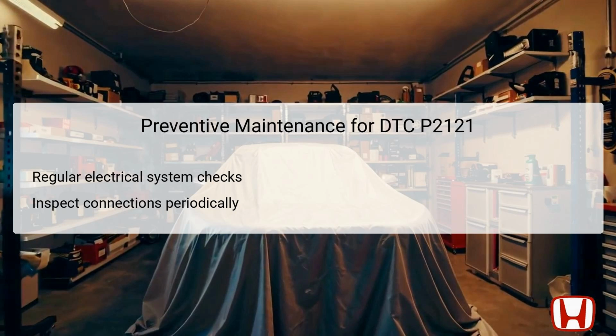It is particularly important to observe conditions of terminals, ensuring they remain corrosion-free and securely connected. Besides physical inspections, ensuring that all electronic components are updated with any technical service bulletins can improve reliability. Ultimately, proper maintenance reduces the risk of sensor malfunction and ensures smooth operation of the vehicle's electronic throttle control system.